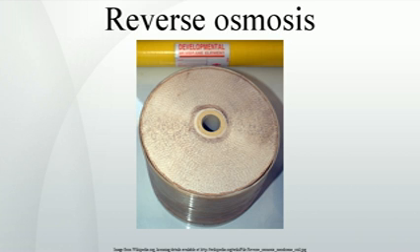The desalinated water purity is a function of the system design. Higher purity needs more equipment and more energy. Purity expressed as total dissolved solids typically varies from 100 to 400 parts per million, ppm or milligrams per liter. A level of 500 ppm is generally accepted as the upper limit for drinking water, while the U.S. Food and Drug Administration classifies mineral water as water containing at least 250 ppm.